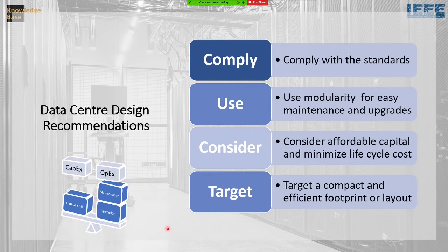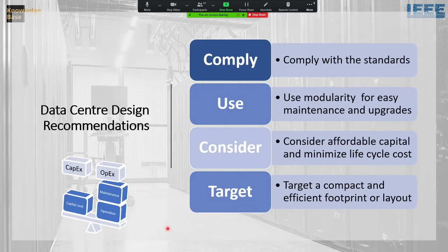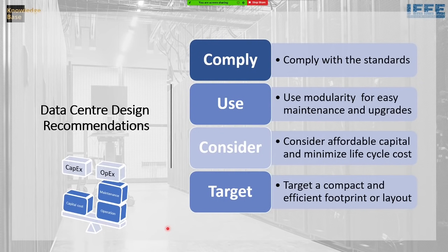One note on the side of the efficiency of using the space in a data center. As you know, in data centers we have IT racks. IT racks are usually 42 units where we fit our equipment, or 48. Now, traditionally, these racks used to host equipment that is 3 kilowatt or 6 kilowatt of power. Now we see racks of 20 kilowatt of power. And why do we see this? Because now the footprint or the size of the equipment is becoming smaller.